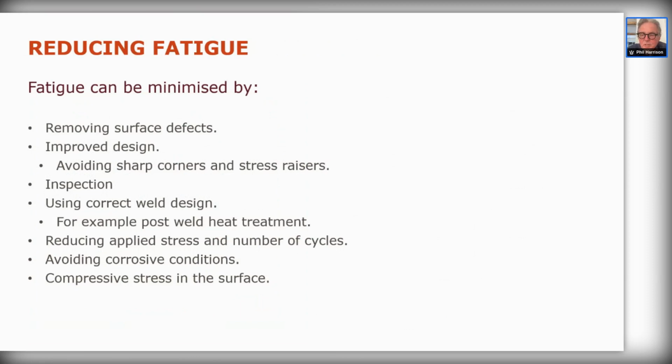The last slide we looked at is something called intrusions and extrusions. This is a microscopic or microstructural effect on metals during fatigue. And what it means is no matter what you do to the material, it will get you in the end. And how do we watch it? Inspection. We can watch crack growth and use fracture mechanics to predict what is happening with materials.